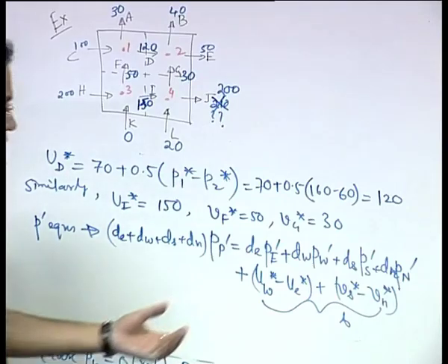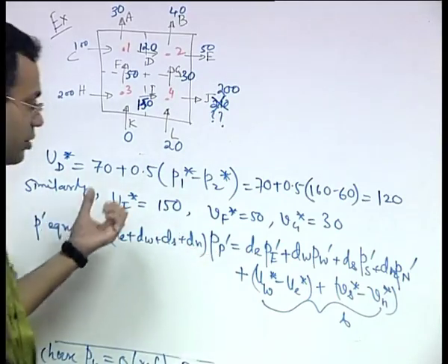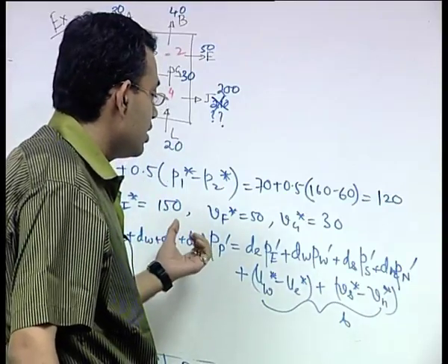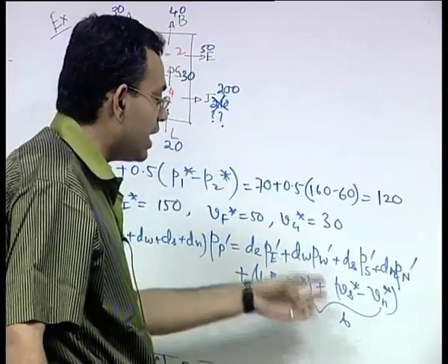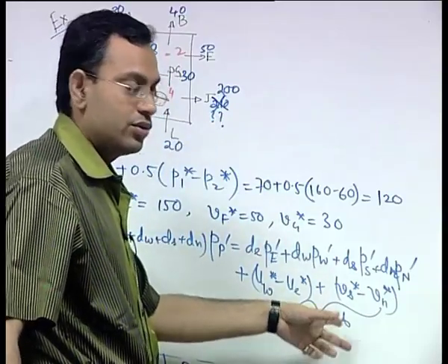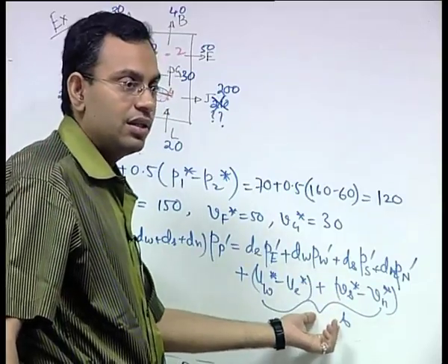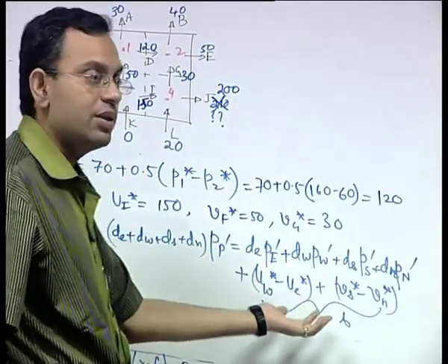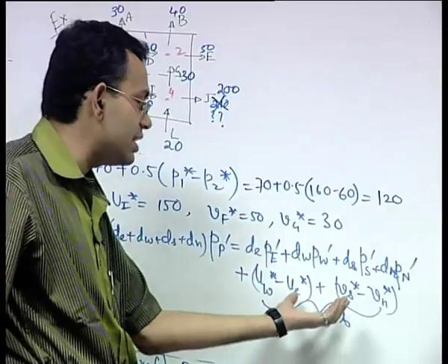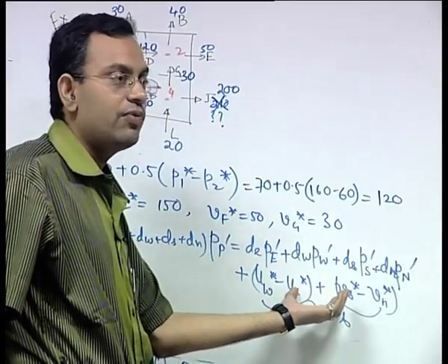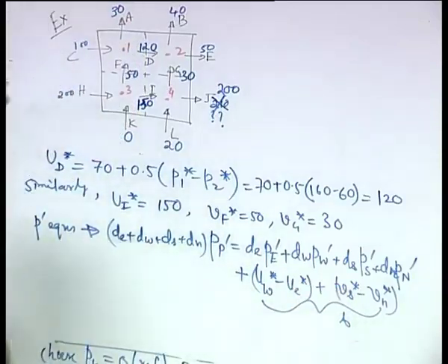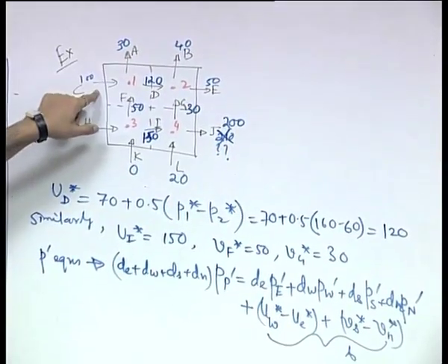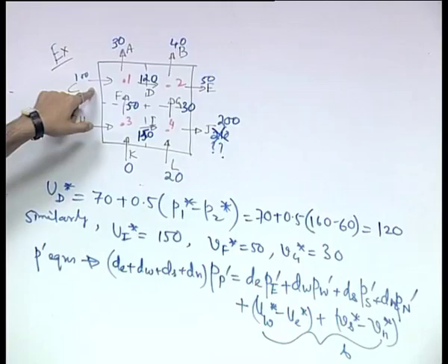So now solving the pressure correction equation, in addition may require to have a relook at the term B. So if the term B is 0, that means it has converged because the continuity equation is satisfied for each control volume, because this is the inflow minus outflow for each control volume. So let us check it for the first control volume, that is the top left. What is the total inflow?